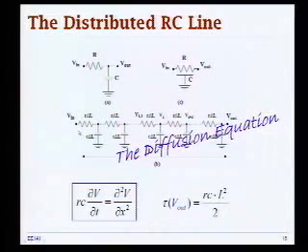And then we analyze this case using this diffusion equation framework, this expression over here, because basically when you inject a step response at the input of this wire, then it basically diffuses through the material until it reaches the final destination, the output, as noted here. And that is described with this diffusion equation here.